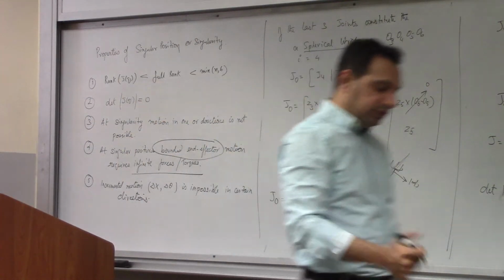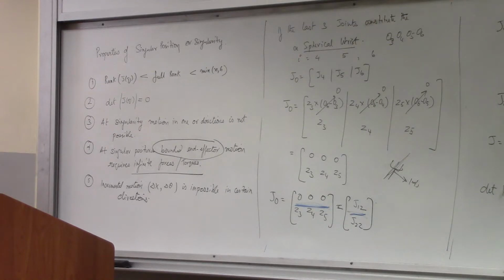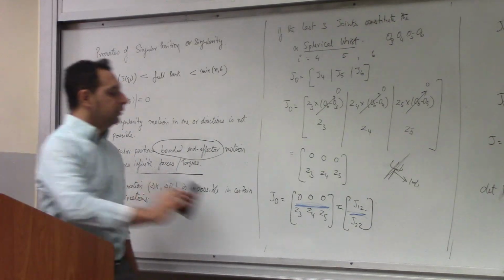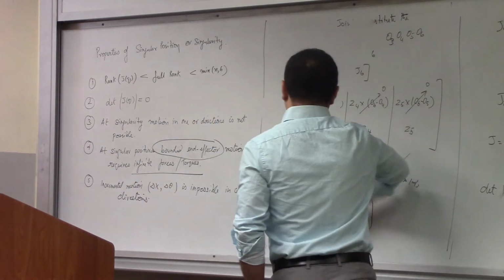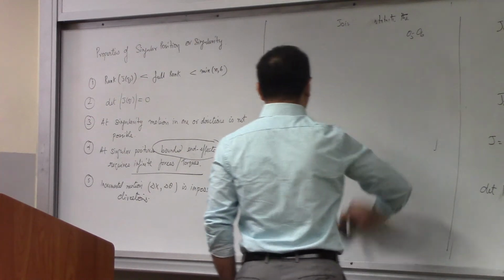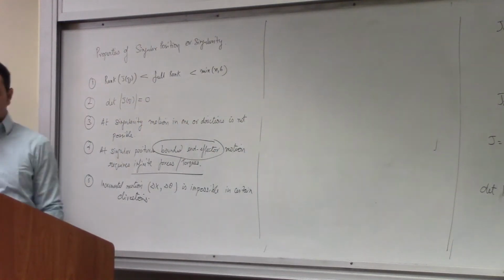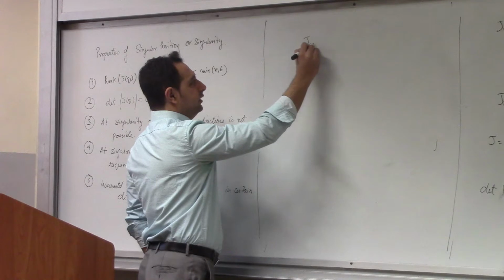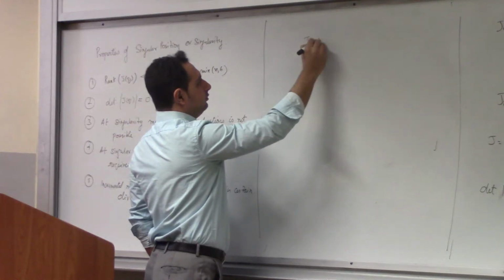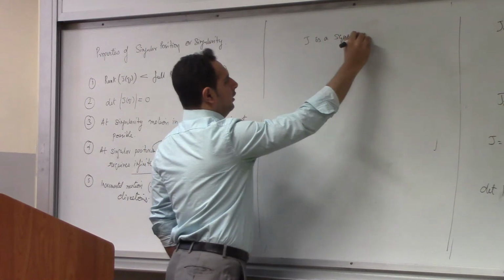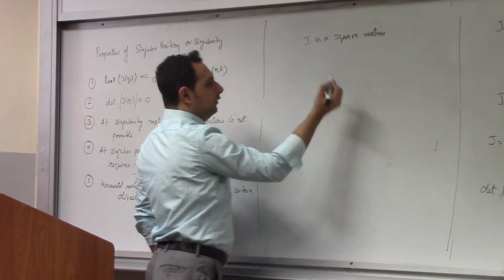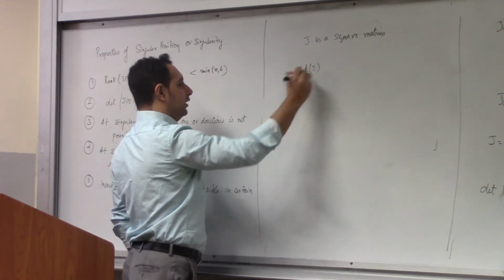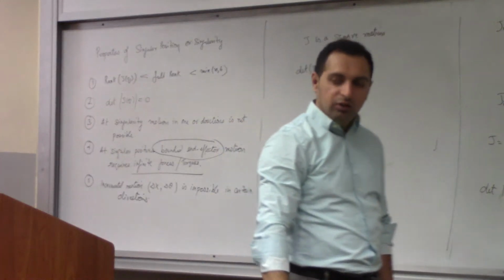So, in some directions, even moving a small perturbation or a small incremental motion is impossible. So this is pretty much the properties of a Jacobian. But if you look at this, there is one big problem that we have not seen yet. If the Jacobian is a square matrix, right, which is 2 by 2 or something like that, you can calculate the determinant because the determinant exists for a square matrix. What happens when the Jacobian is a non-square matrix?